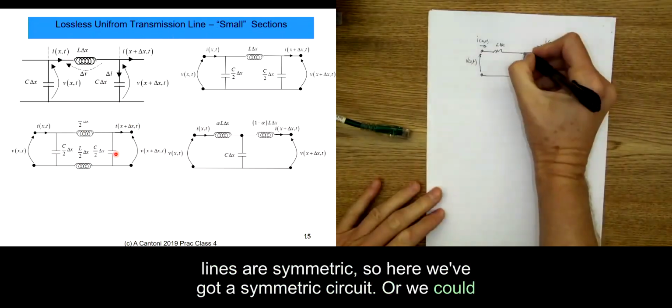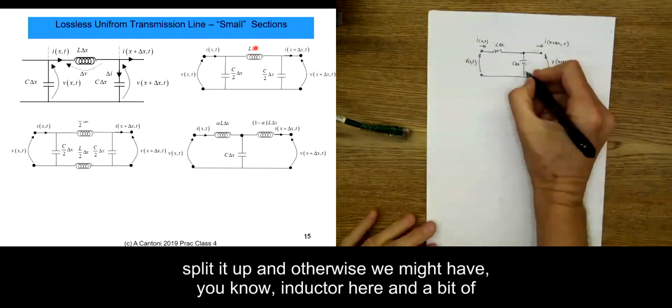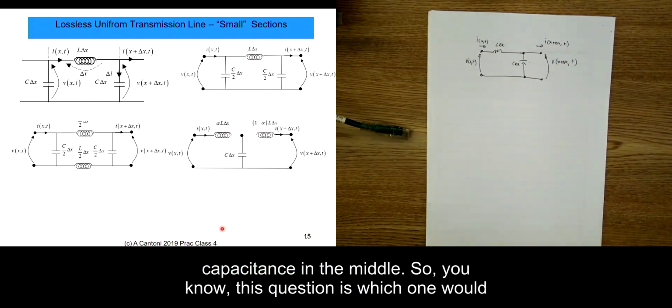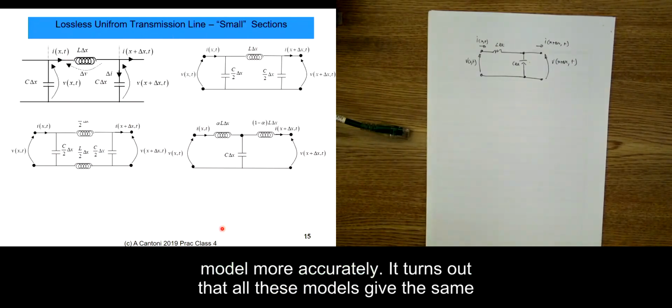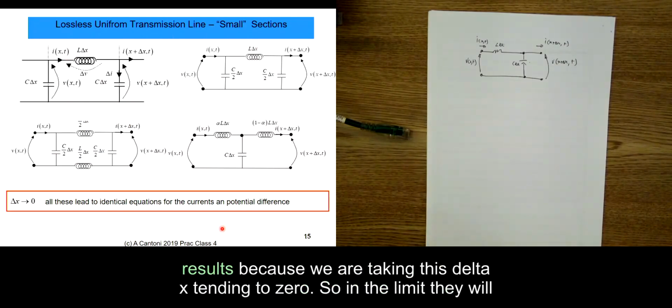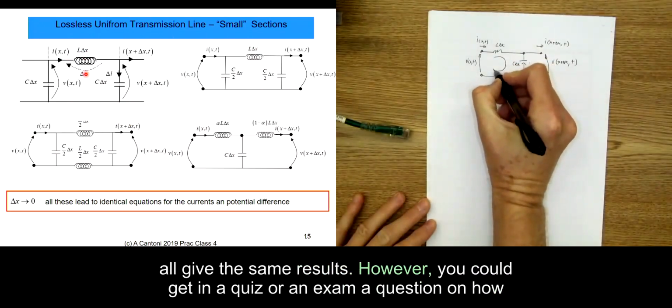Okay, or we could split it up in other ways. We might have an inductor here and a bit of capacitance here and there, or we could split the inductor into two and have the capacitance in the middle. So the question is which one would model more accurately. It turns out that all these models give the same results, because we're taking this delta x tending to 0. So in the limit, they'll all give the same results.